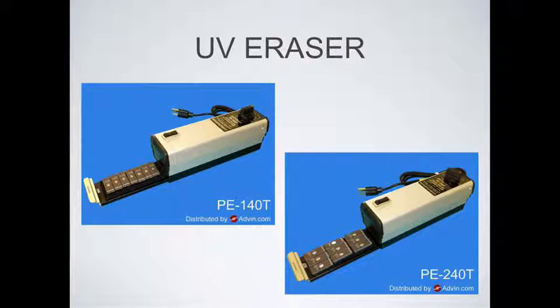Usually what they did in the past was take these chips, write some code, debug it, put it into their system, debug it, find out what's wrong. If something's wrong, they take it back to the UV eraser, plop it back in for 11 to 13 minutes, plop it out, program it again, and then vice versa. This is a whole circular type process. Program, try, repeat. So that's why you would have a UV eraser, and that's why it was useful to have EEPROM, so that you didn't have a slew of PROM chips being tossed away after each iteration. So what's next from there?